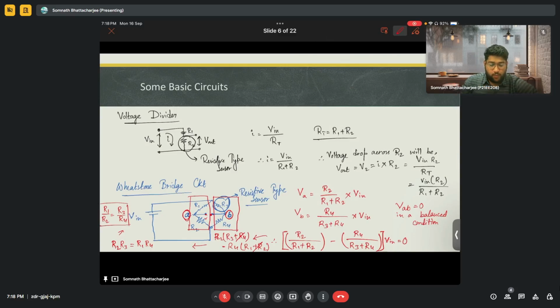So why is it important? As we can see, there are several resistances and those will be similarly affected by an environmental condition. So if a resistance R3 is replaced with, let's say, RS, that is the sensor resistance or a resistive touch sensor, the effect that happens with the RS will similarly happen with these things. So we can have a counter sensor which will negate the effects by the environment itself.